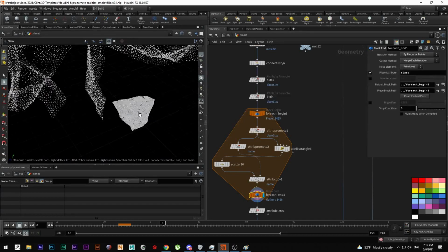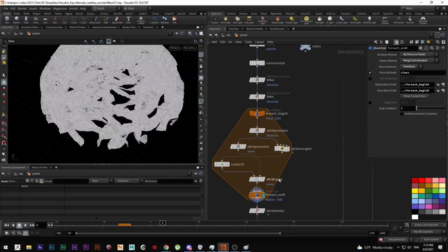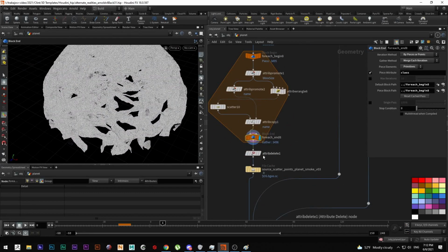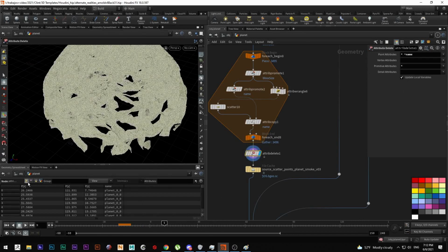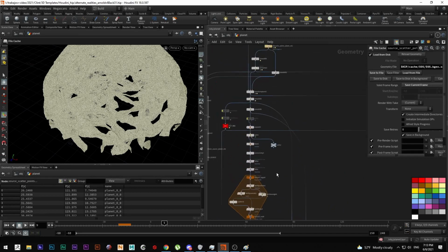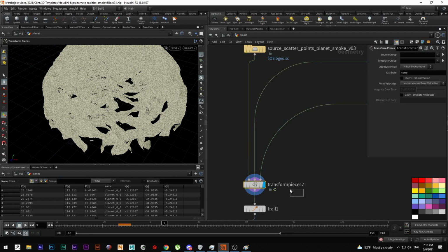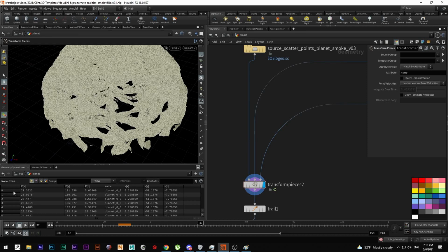But what's funny is that I can control everything. So now that I have this, it's static, it doesn't move. I can delete everything I don't need to save space. I save the points and I point deform them with the animation. Why is this useful? Because if I transform this, the actual point number won't change. It changes position but not number.